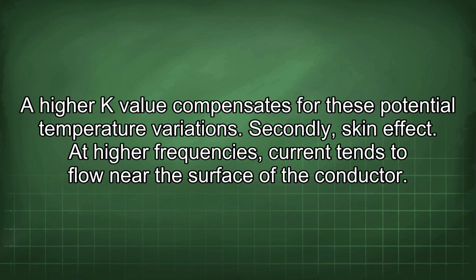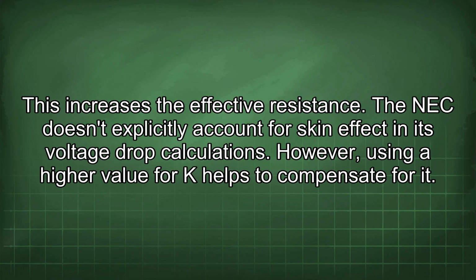Secondly, skin effect. At higher frequencies, current tends to flow near the surface of the conductor. This increases the effective resistance. The NEC doesn't explicitly account for skin effect in its voltage drop calculations. However, using a higher value for K helps to compensate for it.